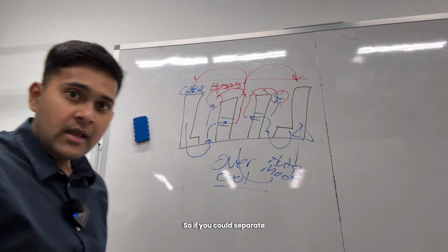There are many different types of cooling configurations in the data center industry, but traditionally you have a raised floor configuration with either hot aisle or cold aisle containment. So for the first configuration, we're gonna showcase a hot aisle containment, meaning basically the exterior is your data center, you have a raised floor a few feet above the ground, you have a plenum or an area above your data center equipment. In between your raised floor and your plenum is where all your data center equipment will be, your cooling systems on the perimeter and your servers in the middle.